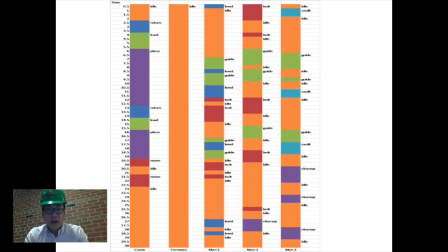The crew balance chart captures the last 2 cycles of placing the foundation wall and sometime past toward the end of the workday. A period of 30 minutes was observed in 30-second intervals. By observing the chart, we can see that the cycle generally consists of the crane loading the wall segment and moving it into place with the workers guiding it.